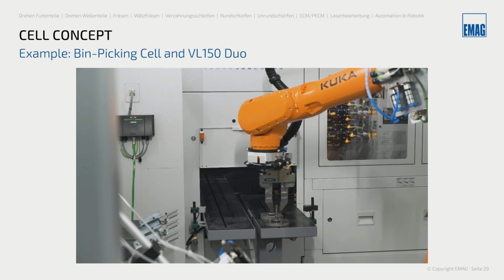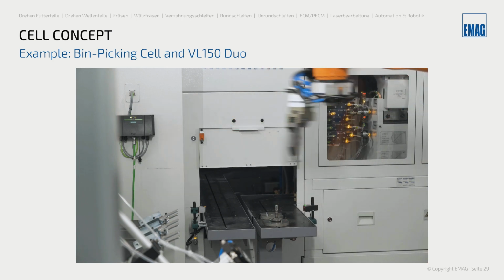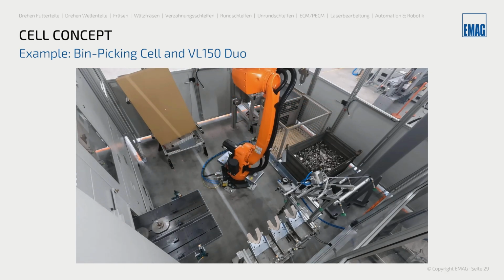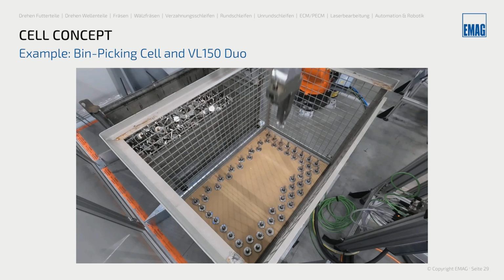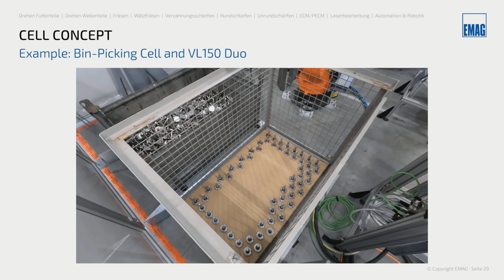You can see how the parts are placed on the machine shuttle. We have less than 1 millimeter of tolerance here because the parts are clamped between 2 fixed pins and 1 flexible pin to maintain a proper orientation for the pickup system in the machine itself. And here the robot placed the finished parts onto the first layer.